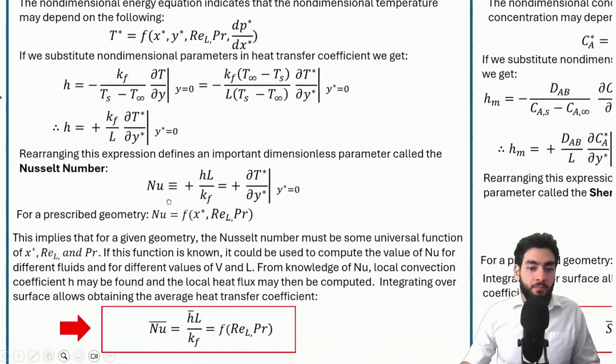The Nusselt number is defined as the local convection heat transfer coefficient multiplied by the characteristic length divided by the thermal conductivity of the fluid. And from the equation, that must be equal to the gradient of the non-dimensional temperature with respect to the y-axis evaluated at the surface.